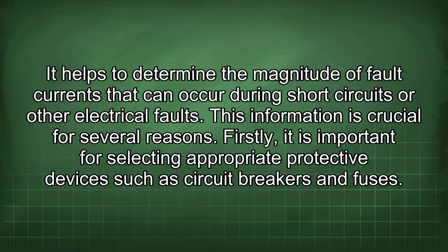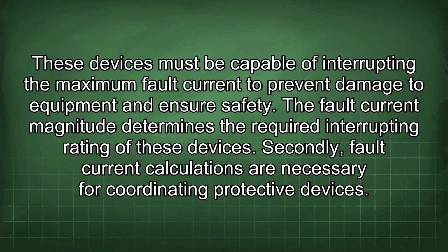Firstly, it is important for selecting appropriate protective devices such as circuit breakers and fuses. These devices must be capable of interrupting the maximum fault current to prevent damage to equipment and ensure safety. The fault current magnitude determines the required interrupting rating of these devices.